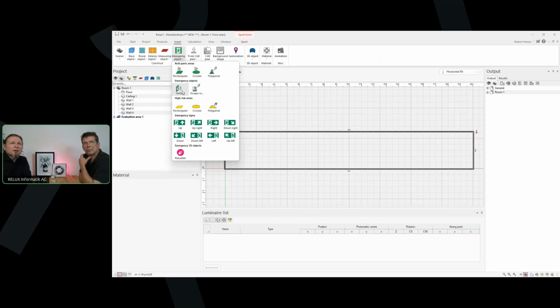And also verticals, to have a minimum illuminance level on vertical stuff at the wall. So most popular is the fire extinguisher, but also some alarm switches, whatever, or a health kit. So any stuff which you can need in an emergency should have a specific value. I guess it's 5 lux. I'm not 100% sure. You need a couple of lux on the surfaces vertically. This is also in place.